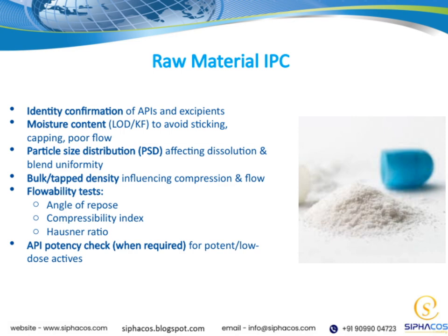We also need to consider particle size distribution, or PSD, because it directly impacts how well the powder dissolves and how uniformly it blends. Consistent PSD helps us achieve uniformity in the final product. Bulk and tapped density are other key parameters. They influence how the material compresses and flows during tablet formation. Good flowability and appropriate density are essential for consistent tablet weight and quality.